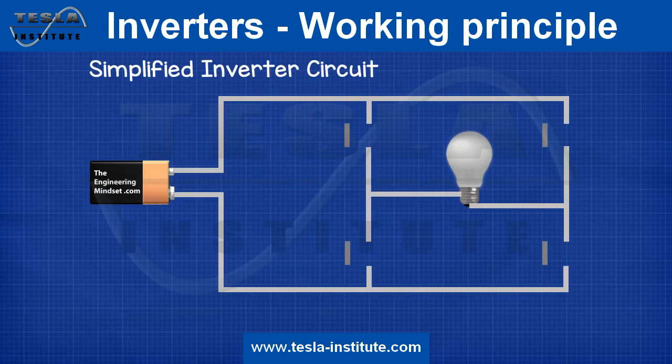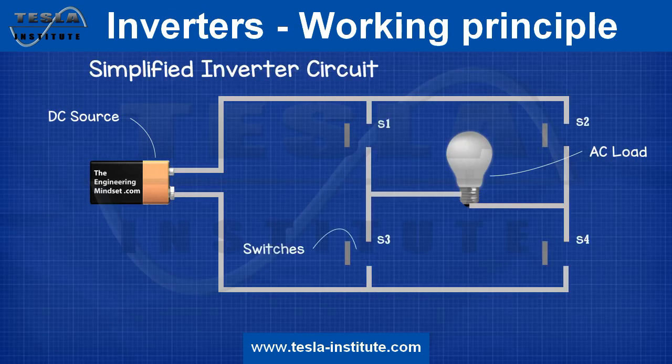Well, let's consider a simplified circuit where the DC source is being used to power an AC load, represented by the lamp. To convert the DC to AC, we will use 4 switches. We will pair the switches together so that switches 2 and 3 open when 1 and 4 close, and vice versa. This will allow us to force the current through the AC load in an alternating direction so that the lamp will experience an alternating current even though it's from a DC source. So let's give that a try.